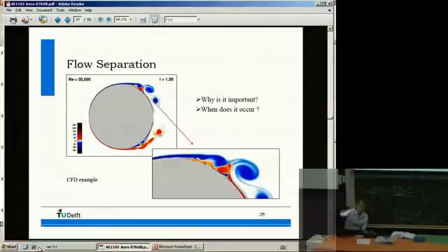But if you increase the angle of attack of your wing, at 90 degrees angle of attack, you have just a bluff body, the flow is fully separated from leading edge to trailing edge. Somewhere in between, separation starts. And indeed this is related to the stall. So the flow stalls, so you get first a small separation bubble, and then the separation moves upwards, and at some point, for a large angle of attack, you get leading edge separation.